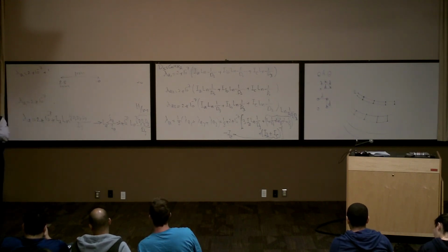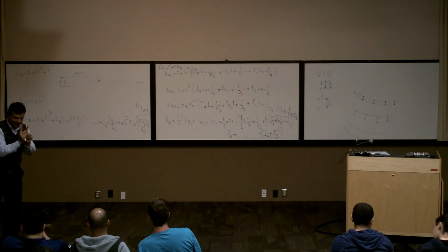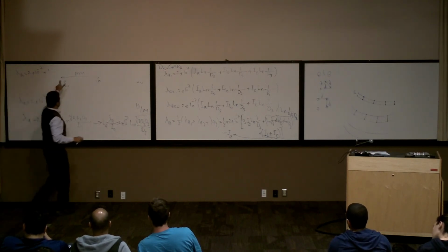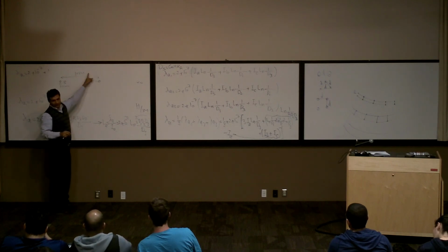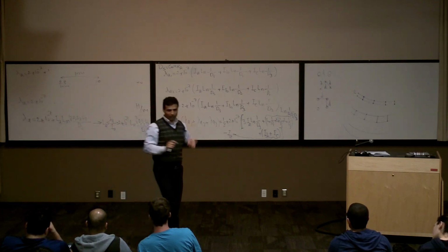And I said, when I talked about composite conductors, if the D is much bigger than the distance between these conductors, it means nothing. The GMD for these two is going to stay this, right? And this two is going to be equal to 1. So the only thing that's going to change is going to be GMR. So how much is the GMR?